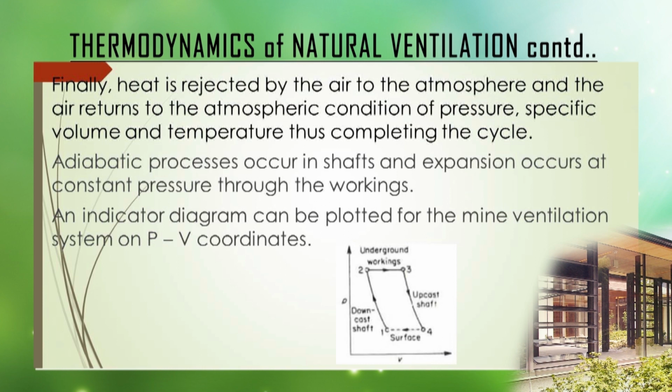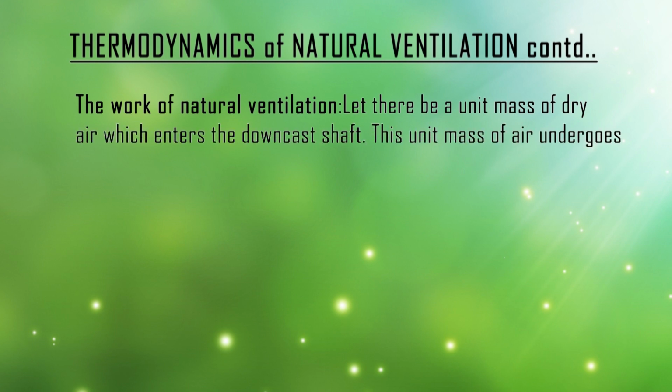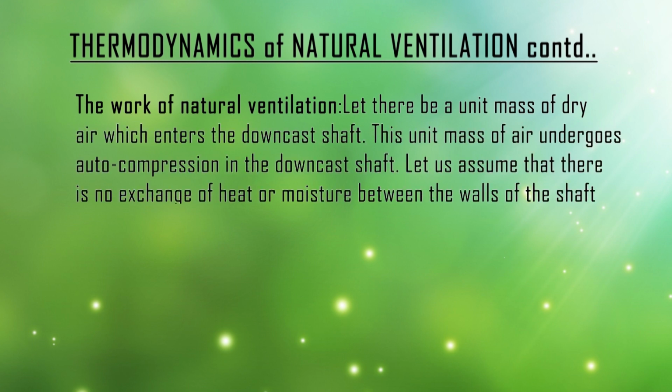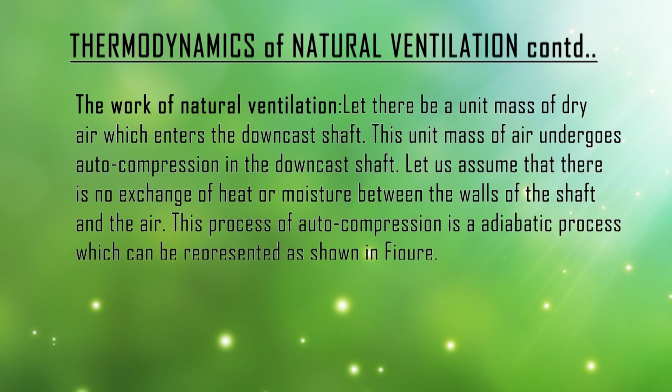in terms of natural ventilation. The work of natural ventilation: let there be a unit mass of dry air which enters the downcast shaft. This unit mass of air undergoes auto compression in the downcast shaft and there is no exchange of heat between the walls of the shaft and the air in the adiabatic process of auto compression, and temperature increases, which can be represented by the graph shown.